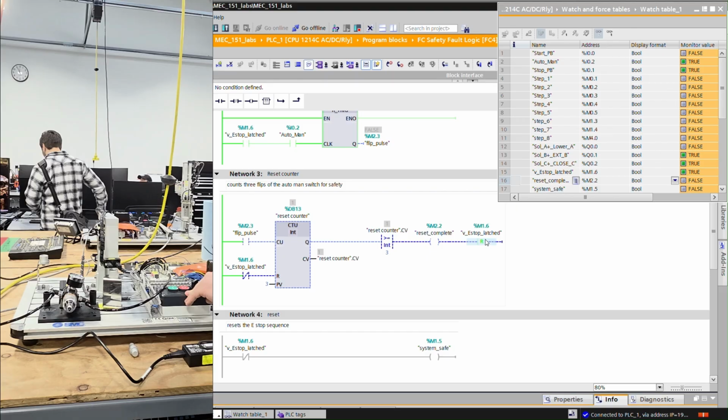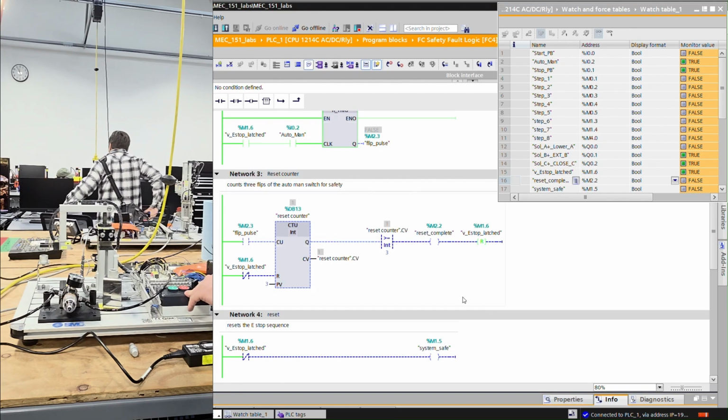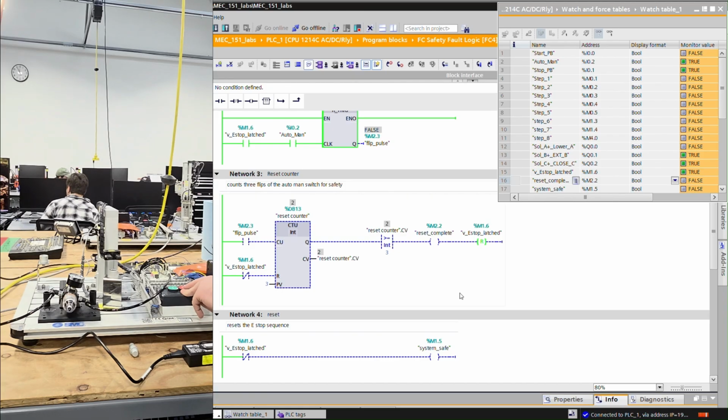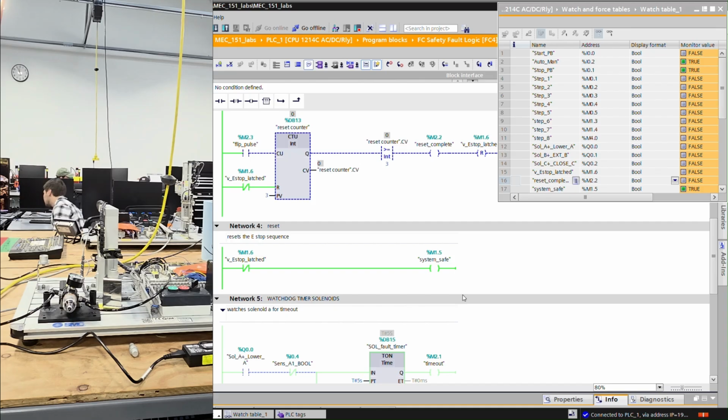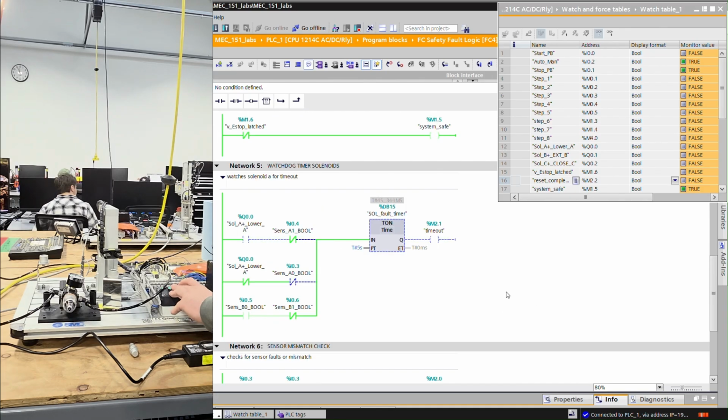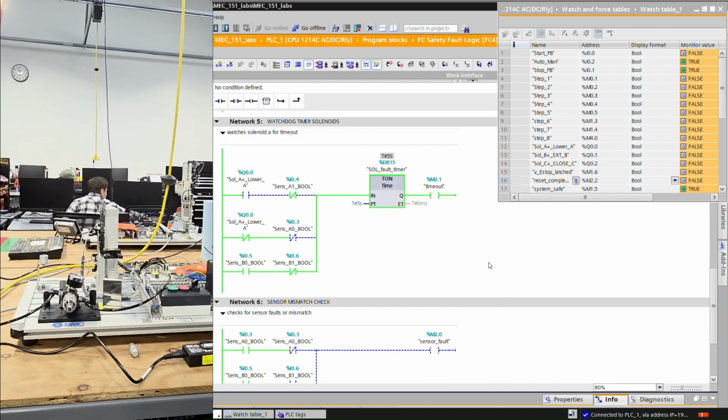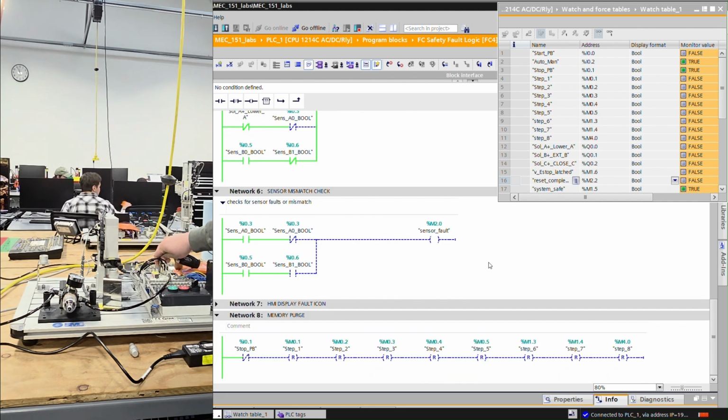However, look closely at the physical hardware. Because dropping power to a single acting solenoid would cause a catastrophic vertical drop or part collision, our safety block latches an internal software lockout flag. This flag maintains an emergency holding loop to the active physical output terminals, keeping the valve coils energized and pinning the arm in a safe, static, frozen position mid-stroke.